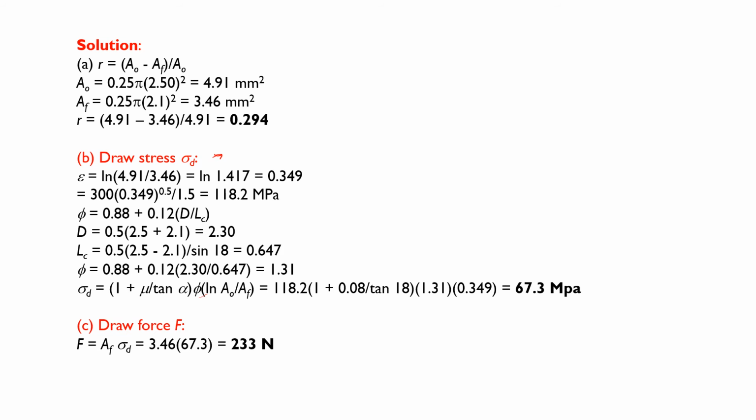Okay, now we can calculate the epsilon here. So epsilon equal to ln 4.91, which is already given here, over the 3.46. Okay, and then you will get the strain. Okay, so this is the strain, and then based on this one you can calculate the value here. Okay, so this is the YF. The YF equal to 118.2 MPa.